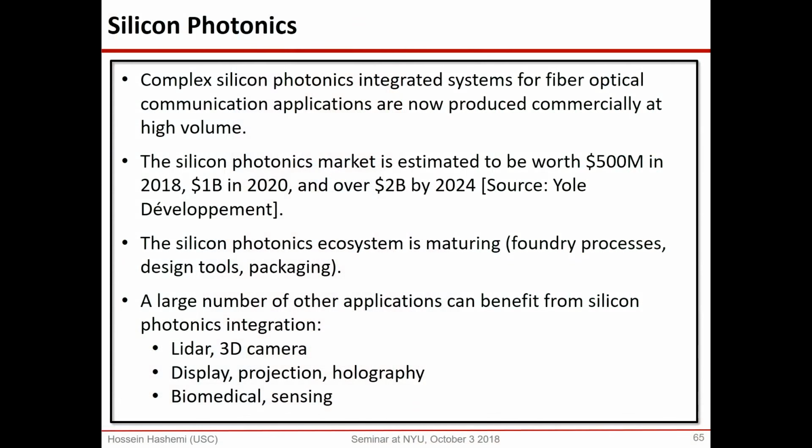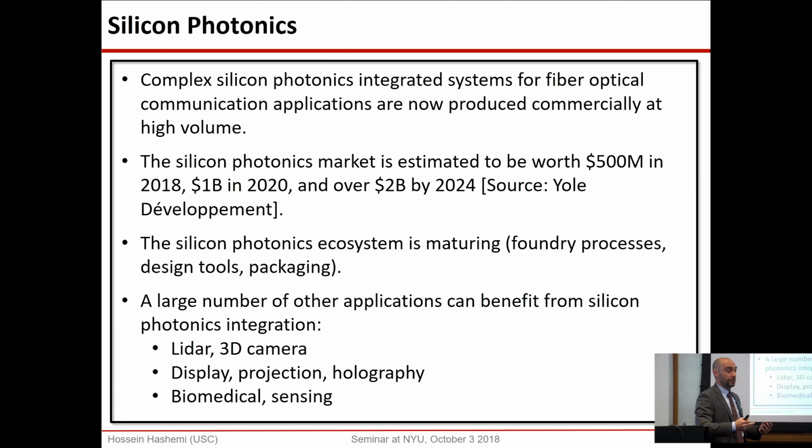LiDAR, how many of you have heard of LiDAR? All right, so LiDAR is basically the equivalent of radar, except that it works with light. So I send out light and it comes back from an object and I decide where it is. It's made a lot of noise lately because of its potential application in self-driving cars, right? So I told you that radar is one application for self-driving cars, LiDAR is another way, and camera is another way.